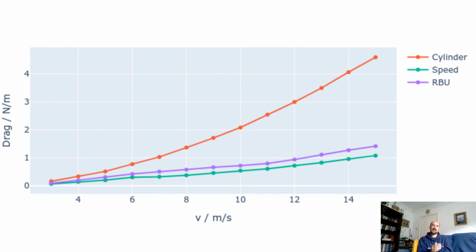So in the earlier videos when I said the parasitic drag increased proportional to the square of speed, well, that's roughly true, but in real life these mathematical approximations don't always hold exactly, because that was assuming a constant drag coefficient, and you could see from the previous graph that the drag coefficient isn't actually constant.